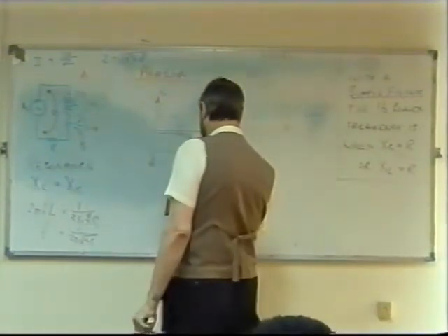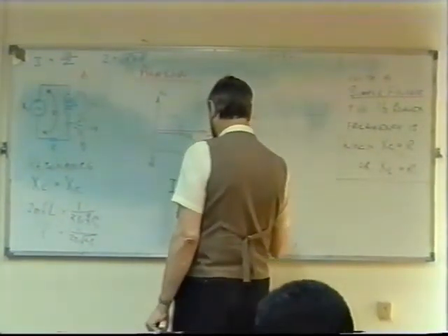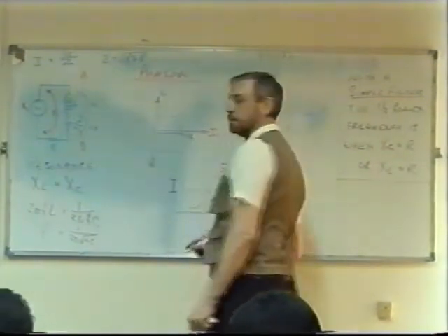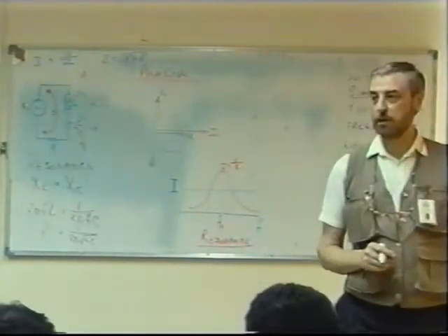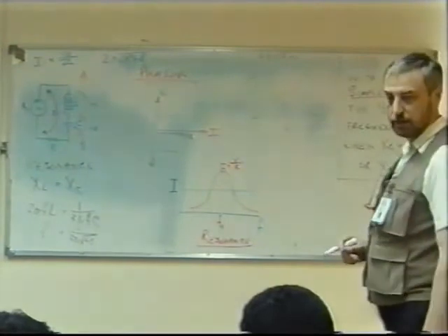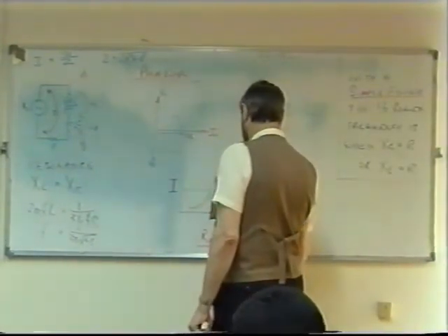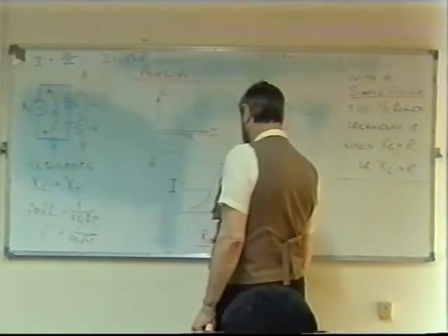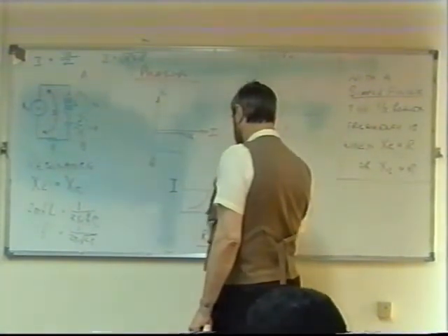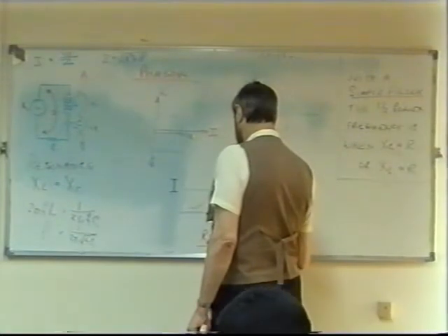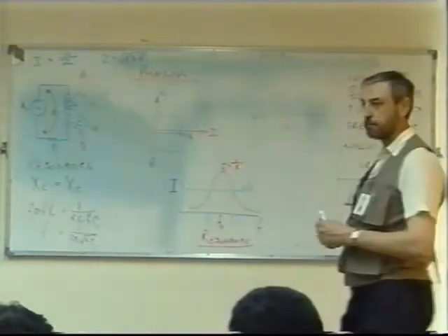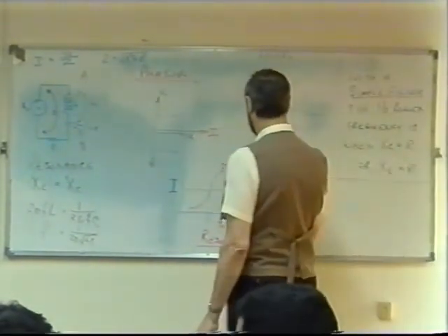In a bandpass filter, we have two cutoff frequencies, don't we? Yes. One above and one below the resonant frequency. These are our half power points, and these are half power frequencies. So this would be a bandpass.